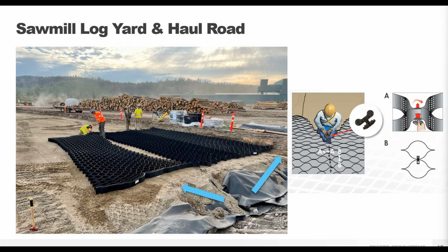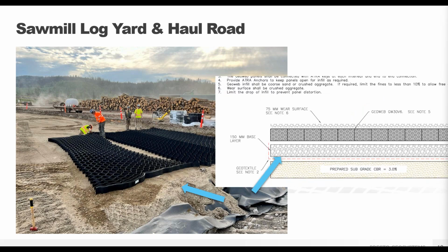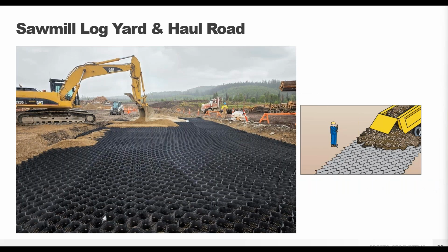Here we see the GeoWeb sections expanded and the workers are just beginning to connect panels side to side with the AtraKeys. This design included a permeable base layer with less than 10% fines for stormwater purposes. The GeoWeb system provides a strong reinforcement layer for the constant heavy loads that the mill infeed area sees daily.